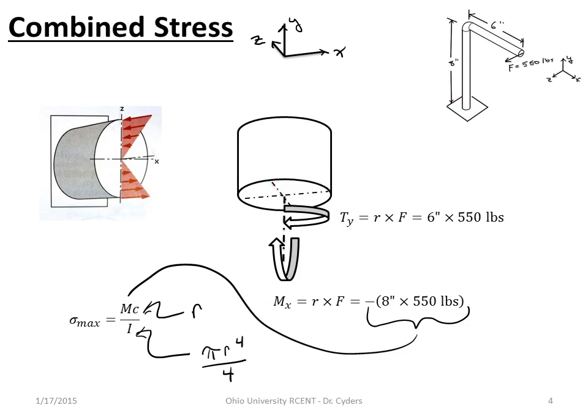Now, how that works with a combined stress, we could check at the opposite of point A, on the back of the cross section, and we would see from both of the failure criteria that we'll talk about in a later slideshow that those two will actually be equivalent, but that's beyond the scope of this discussion. At any rate, we have a bending stress distribution, which should look pretty familiar, and so we're going to have bending stresses at A, but 0 stresses at B, again because of the neutral axis.